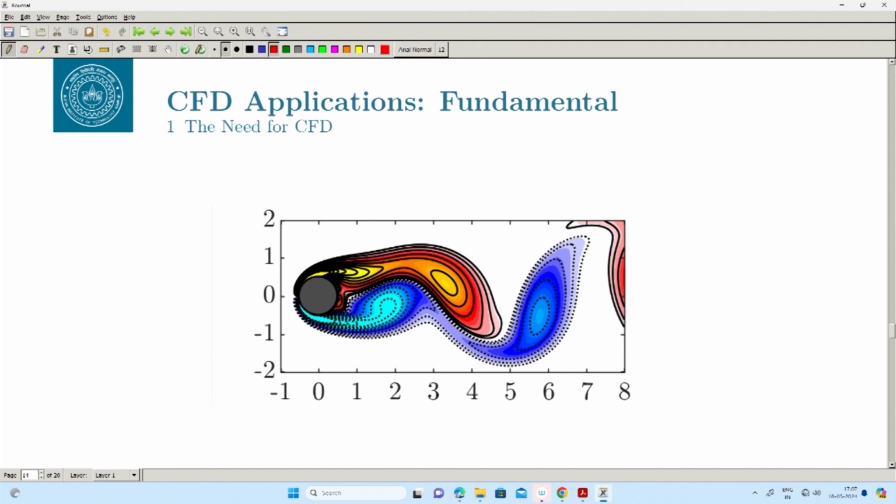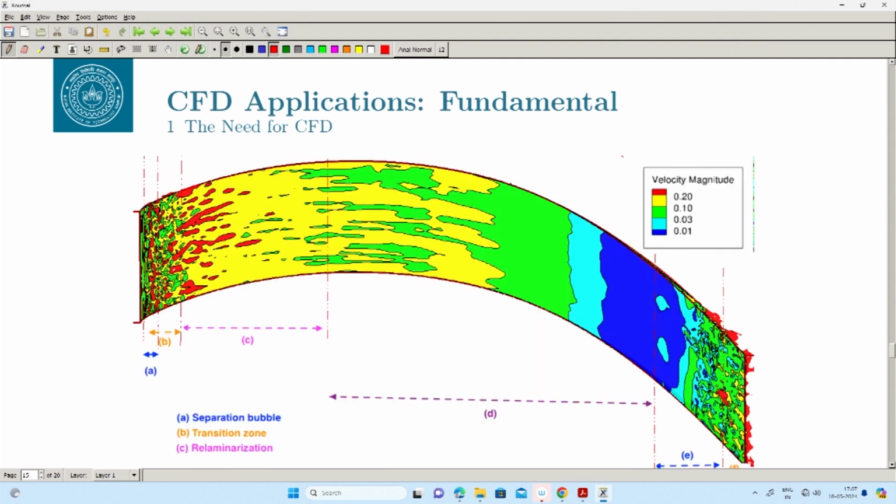Okay. And initially, because the computers were not very powerful, we were limited to 2-dimensional simulations, and as the computers became powerful, now you can basically simulate more complicated systems. Okay. So, for example, this is a flow past a cylinder. You can see the very nice vortex shedding, and you can find out the shedding frequency which is changing. Okay. You can increase Reynolds number and Mach number and see how the fundamental properties are changing. So, you can easily do these kinds of things using CFD.